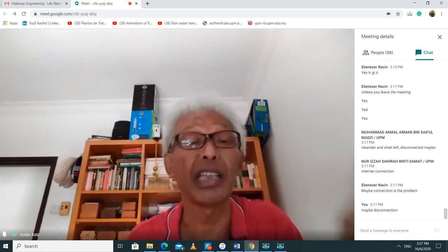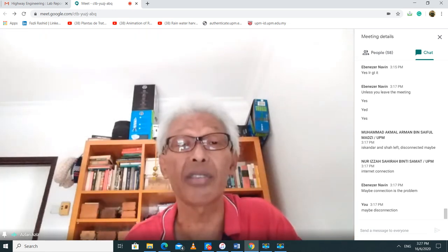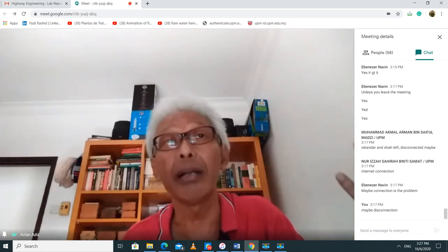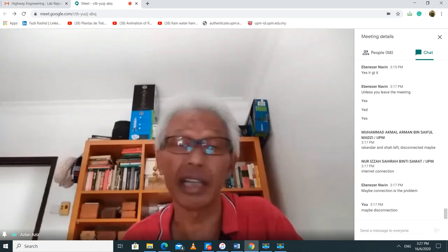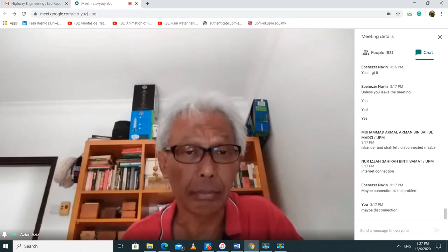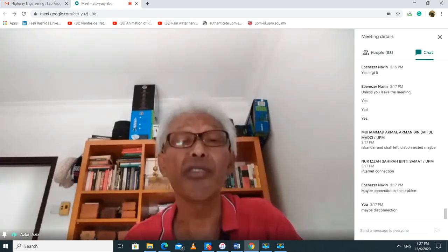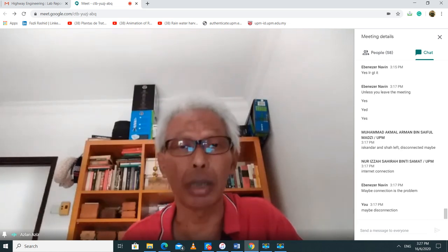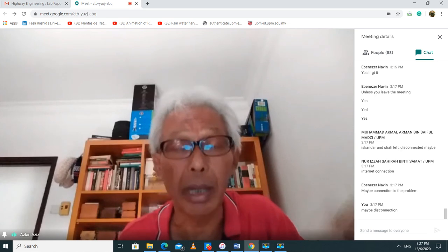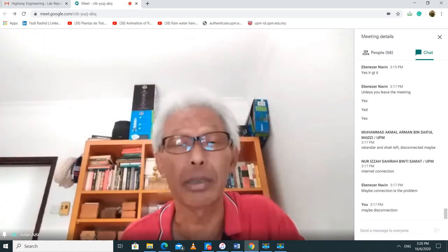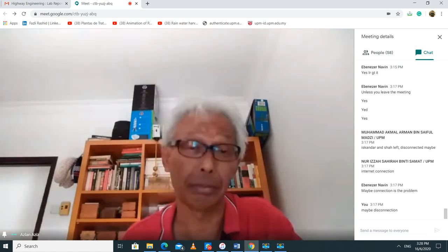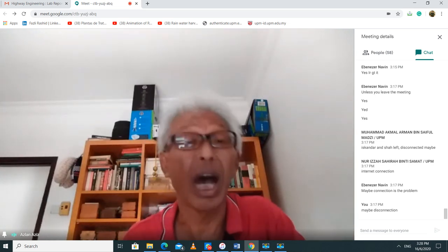Because you see, unlike my cheek here, when I release that excess pore water pressure, which is so quick, all right, to build anything on my soil, it takes about 3 years minimum. All right. Consolidation, you remember that observation? It took years to occur because it's so slow. All right, that dissipation of excess pore water pressure through drainage, so slow.